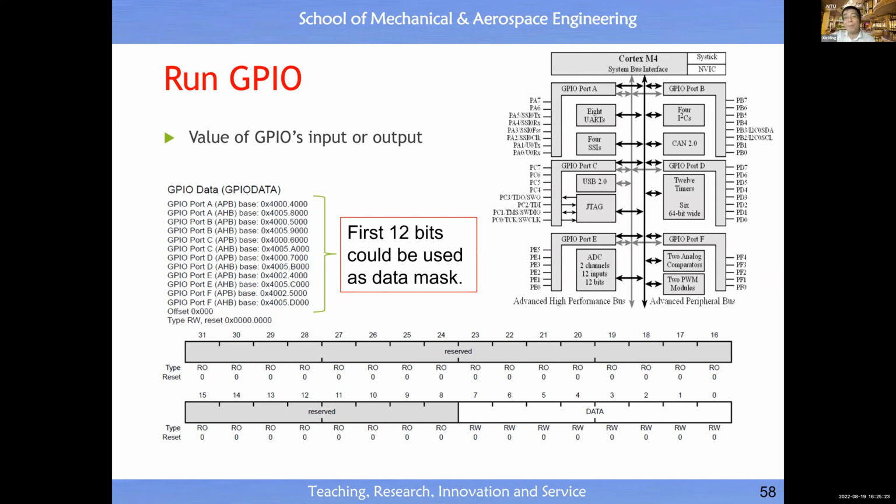Then logic 1, you remember, after that you connect to an electronic switch. Then that switch is switched on, and the current will flow inside your motor already. So it's very simple. So the first lecture is important. Basically, the microcontroller for one phase just outputs 2 signals, because one phase you have 2 N, right? You just output 2 signals. 2 signals means without the hardware support. With the hardware support, just 1 signal will do.